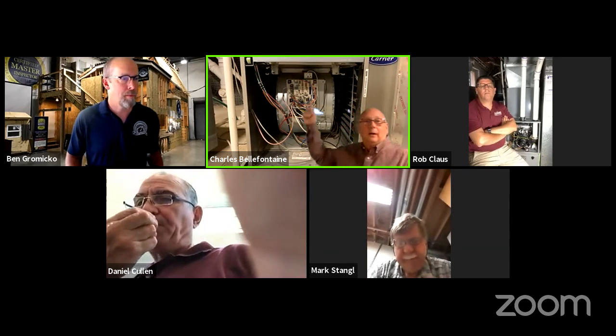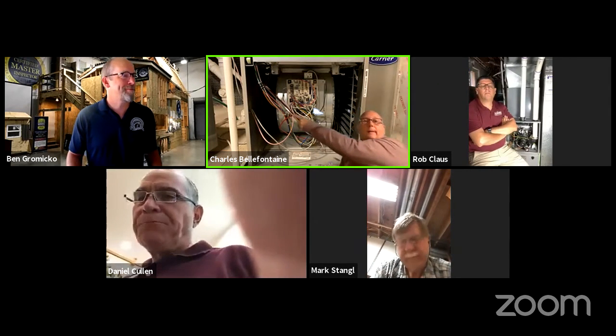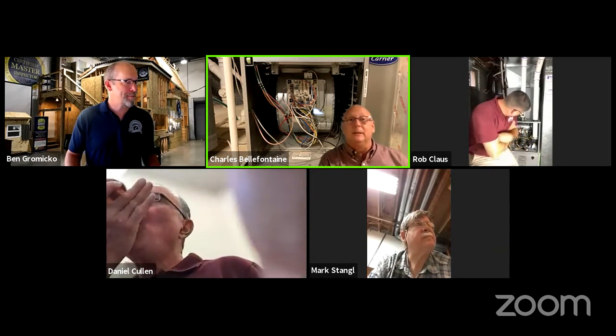Then we're also gonna see if I can do this right. Way up there is the blower door cutoff switch. And you could probably see it. I'm not gonna be able to do that. But all the way in the upper left of your screen on the furnace, you see that white little switch on there. Make sure those are connected. If you're calling for heat, obviously it shouldn't start up when that door is off. That's kind of the simple things.